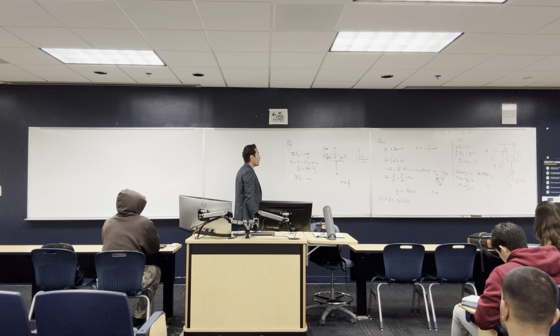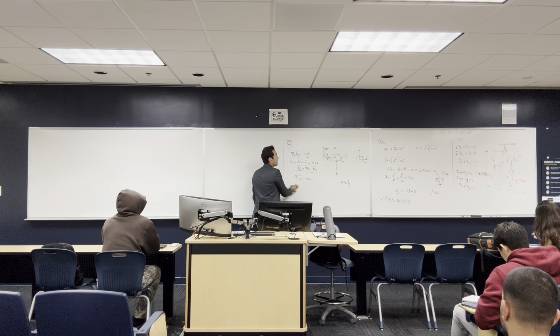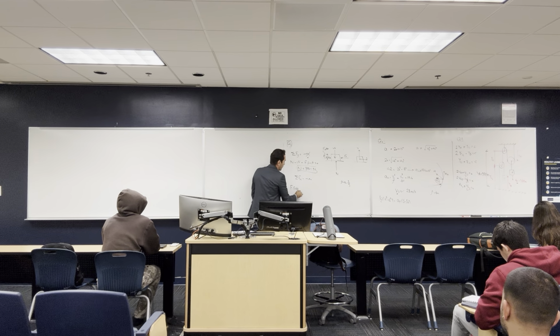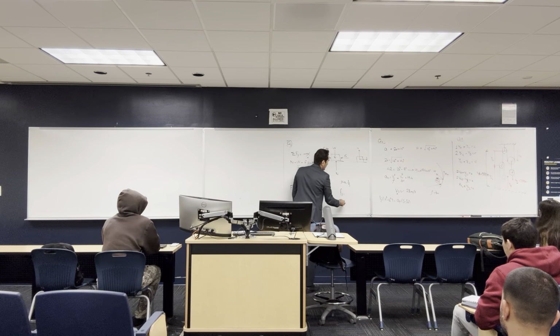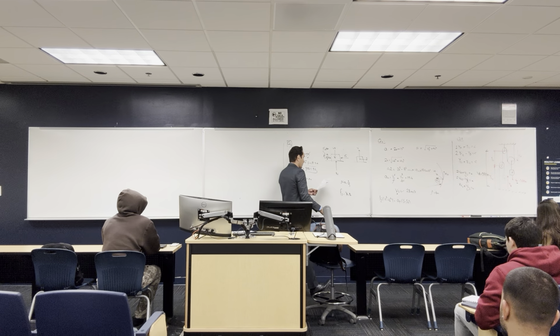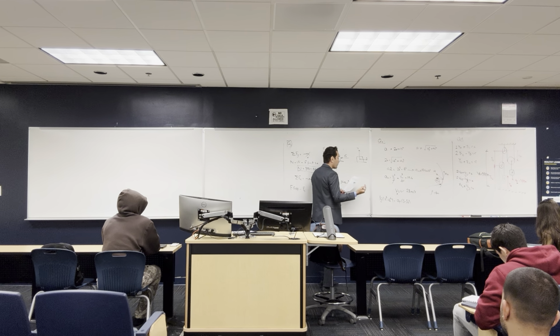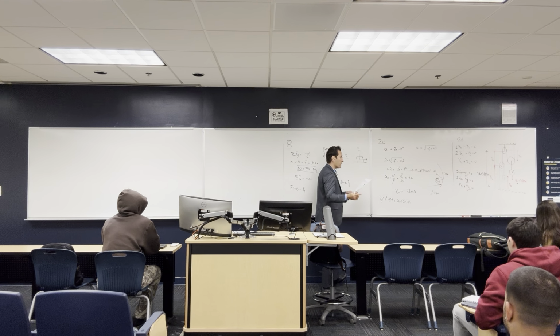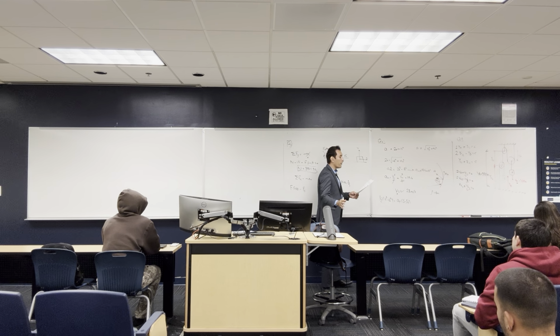So you got N. And here, the forces in the X direction, you have F cosine theta going that way minus the F in the spring. And we all know that the F in the spring is equal to K multiplied by the delta in the spring. So I told you in the problem, if the block is subjected to a force 500 Newton, determine its velocity at S equal 0.5 meter.